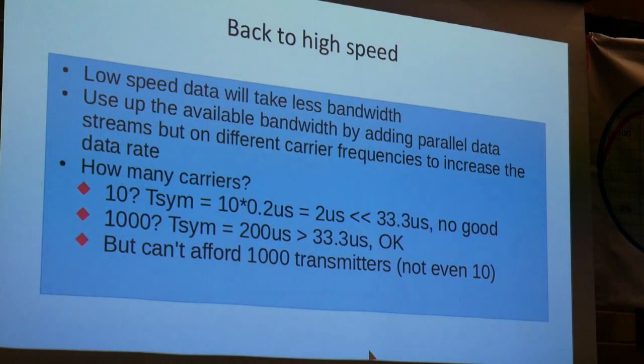And because you're reducing the data rate on each carrier, the bit period is getting longer and longer, and you can make it so long that you can start to ignore the reflections, basically. And they do that typically with a guard band or guard period where you say, I don't care what happens here, I'll wait until it's all settled down. I've got the reflected signal, I've got the direct signal, they've got the same data in them, they're adding together usually, which is really good, so I'm getting even more signal thanks to the reflection.